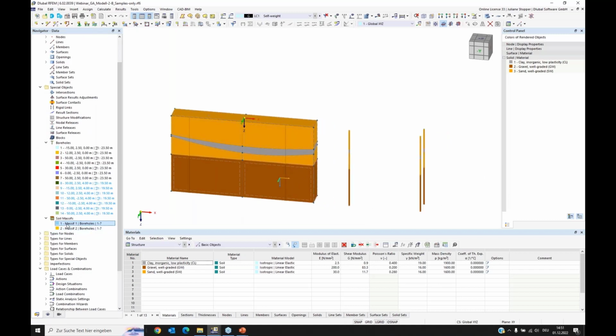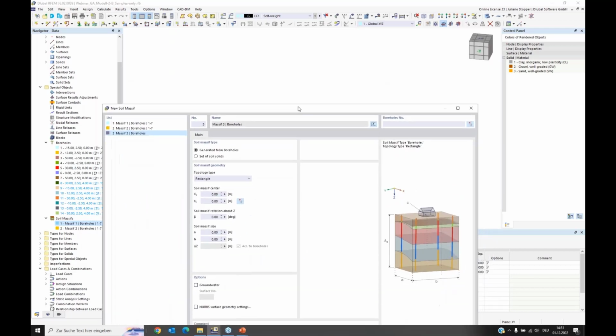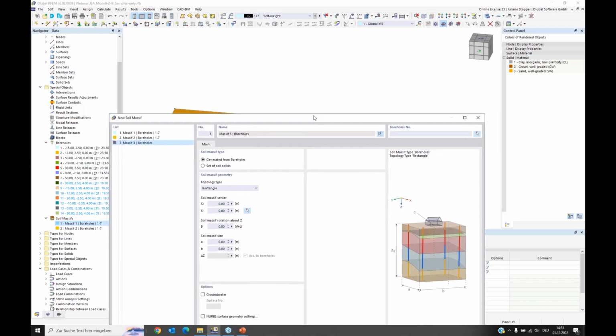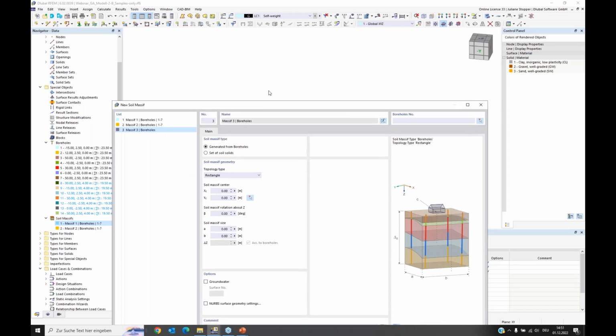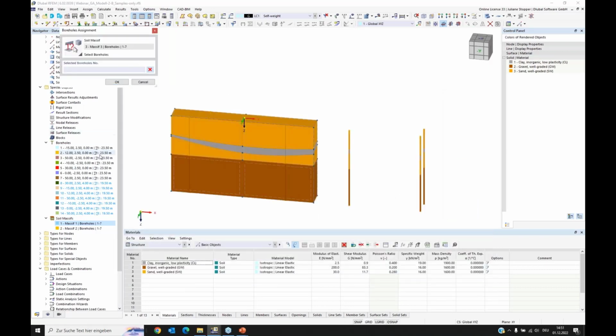Okay, what I can do else is define a new massif, and I want the surface to be at a deeper depth. So I will use a copy. I copy this massif, and it will be placed at 30 next to the previous one, and I will use other boreholes. For this case, I prepared a copy of these boreholes, and in that copy I set another Z value, and the height is different. So you will see the effect soon.